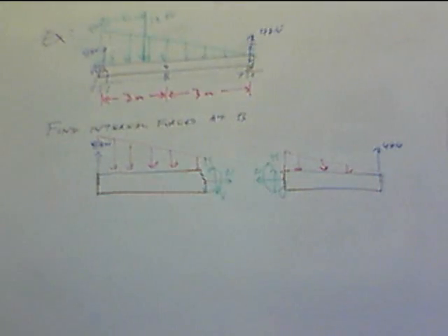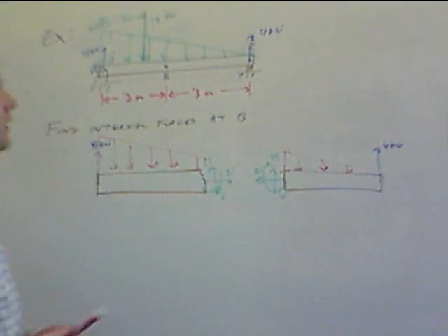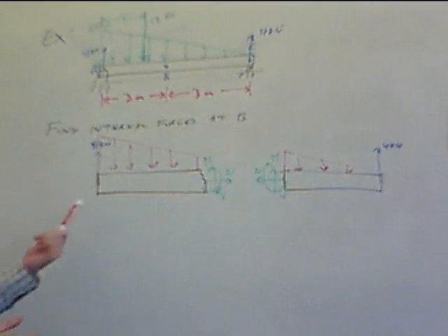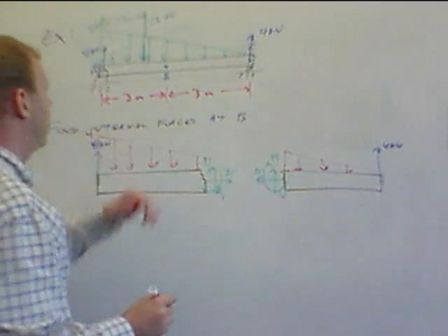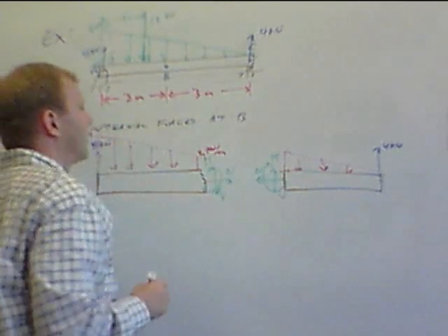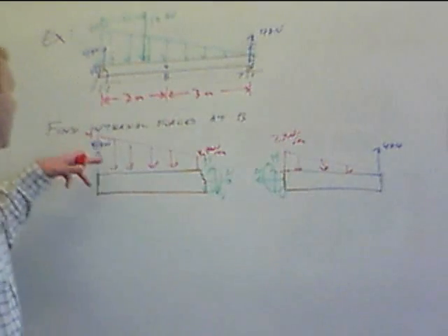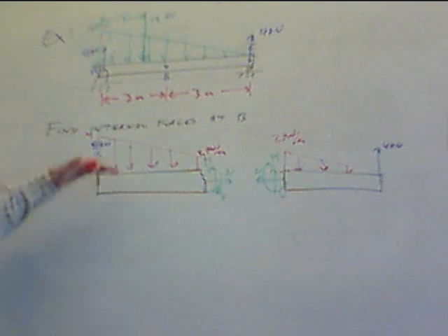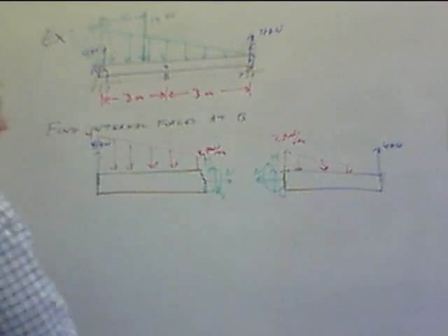Now we need to simplify those individually. This one is now a trapezoid, okay? This one doesn't look like a lot of fun. This one is a simple triangle. This one we could simplify it. I could find the area of this piece. This is 4 up here. Halfway through this is going to be 2 kilonewtons per meter. This is 4 kilonewtons per meter. This is the same 2 kilonewtons per meter. Okay, I could do this. I would have split this into a rectangle and a triangle and reduce the distributed load and go for that. I'm not going to bother doing it the long way.